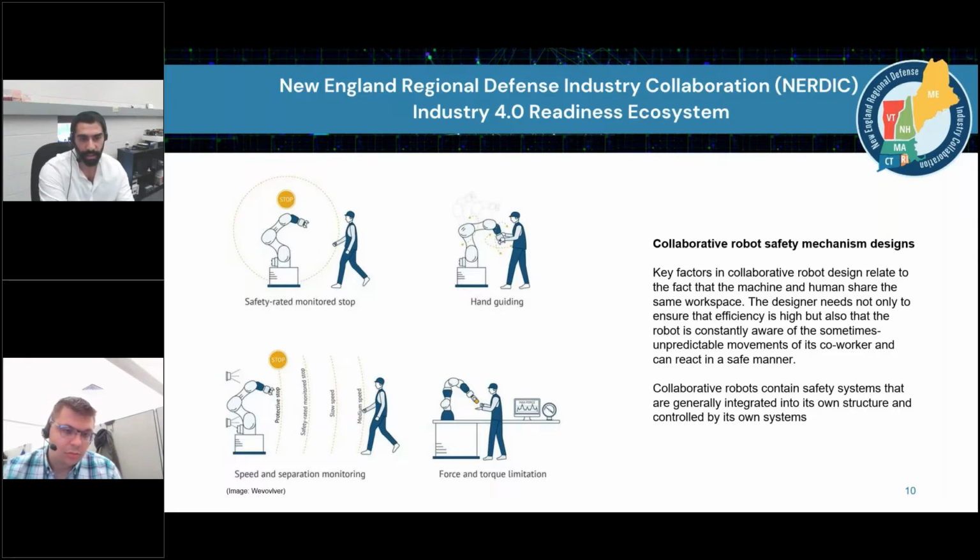Contact can either be quasi-static, such as the clamping of a part, the pinching of the robot arm or the work part and a worker's body, between the robot manipulator and a fixed object. Or it could be transient, such as the knocking into a part of a coworker's body where the worker is able to recoil.